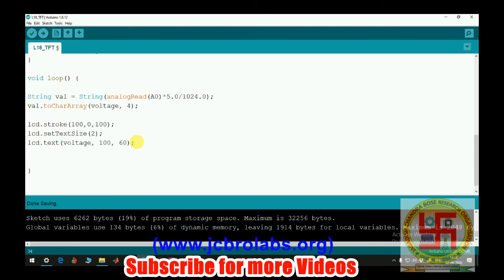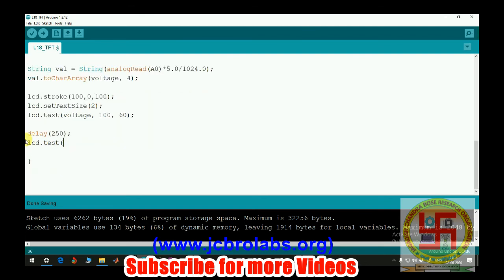Now we want to update it. In order to update, first of all we need to clear the previous screen. So we'll make a delay of 250 milliseconds, and then in order to clear the text, we will display the text again with the same color as that of the background. Remember, if you want to clear any display, make the text color the same as the background, because in this library there is no specific command to clear the display.